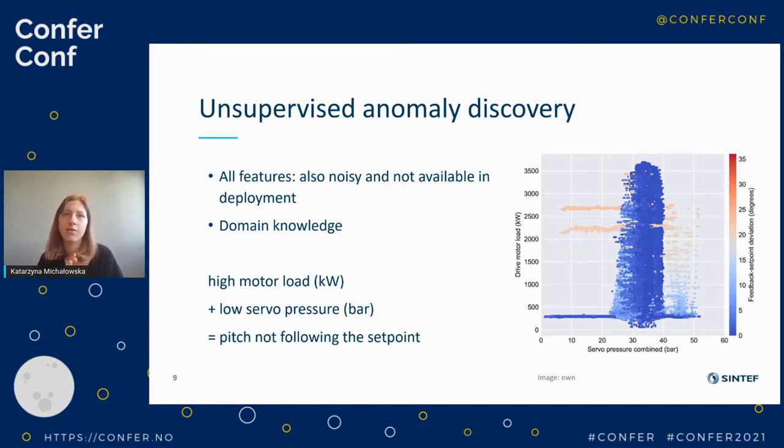We have noticed that if the drive motor load was high and the servo pressures were low, which here are clear outliers, the pitch was not following the set point as good as we could. So that gave us a label on these points which were anomalous there in a much easier manner. In that, it needs to be mentioned that it's also always great to contact your experts and ask them about what they think should be used to detect some anomalous behaviors.